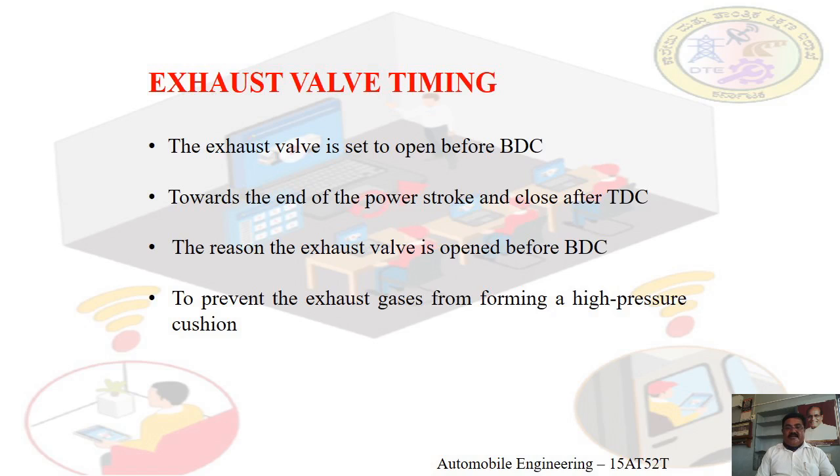The reason the exhaust valve is opened before bottom dead center is to prevent the exhaust gases from forming a high pressure cushion.